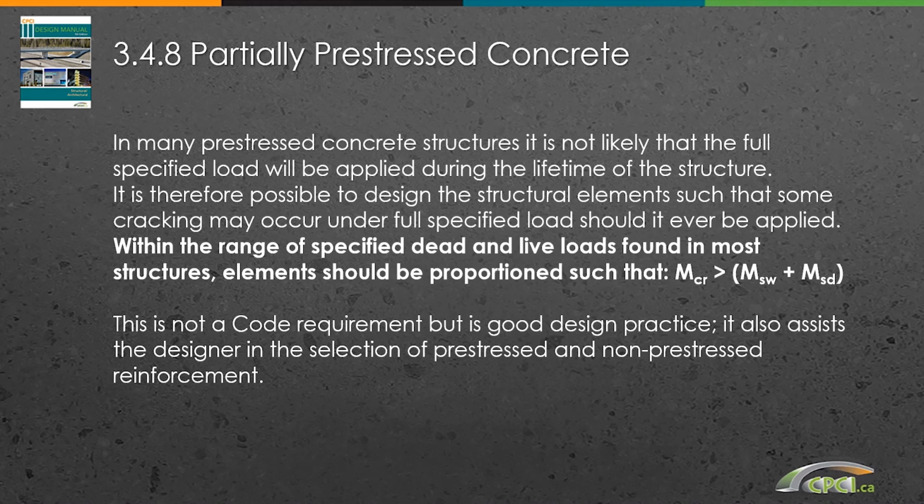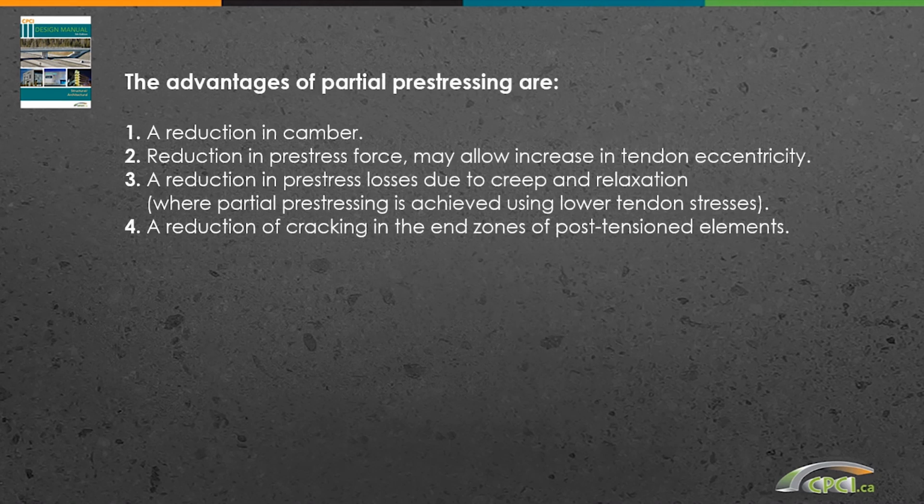But the partially pre-stressed concrete is a good feature. It's not a bad thing to use it all the time, or not all the time, at least most of the cases, because it has major advantages. It reduces the number of strands in a section. It reduces the camber. It reduces the pre-stressing forces. Therefore, it reduces the losses, and also if you are post-tensioning, usually you have some cracks at the end due to the post-tensioning force.